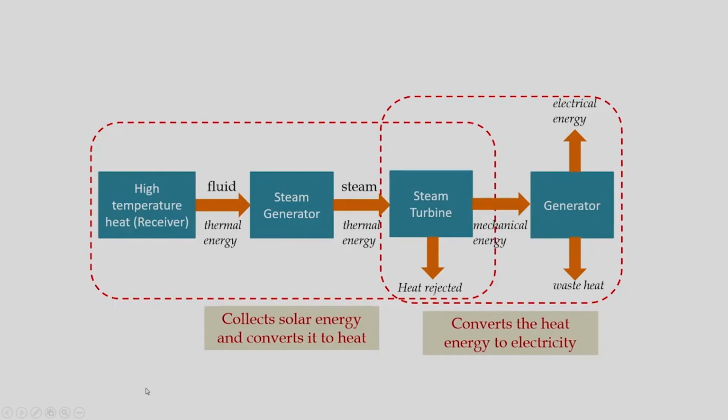Now, let us see this picture, how this high temperature heat which is generated in the receiver system. Okay? So, as you can see, thermic fluids are used in the tube through which heat exchange takes place, solar radiation. So, maybe this is the collector. So, heat radiation falls here, beam radiation falls here and strikes in the receiver system. Okay? So, heat transfer fluid flows. So, here this heat will be very high. If we talk about the parabolic trough, maybe 350 to 400 degree C, it is a very high temperature.